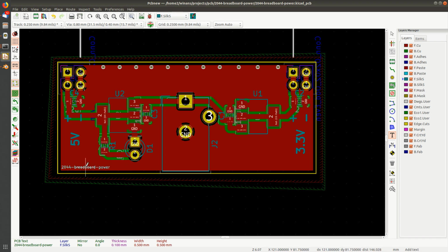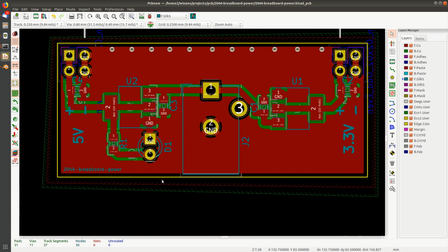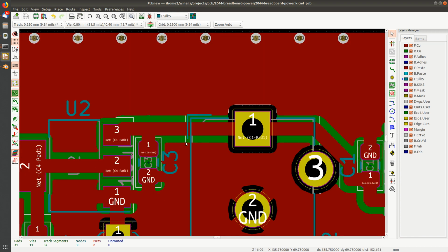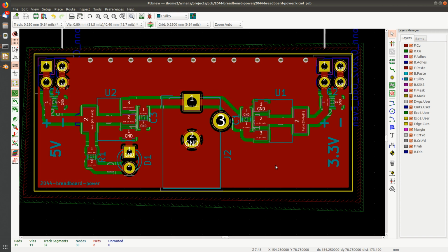So, and that's another thing you want to do when you send out your first board. Do a cheap one the first time you use a vendor to make sure they know that they can make what you want them to make. Send a test board over there with some extreme distances. How close together can your copper be before they accidentally put shorts in here and stuff like that. You'll want to do a test board. Fortunately, this board here will probably cost $5 or $10, and you'll get 3 of them, including shipping, which I consider a pretty good price. You can get the board for less, like from China or something like that, but then you got to pay $20 in shipping.